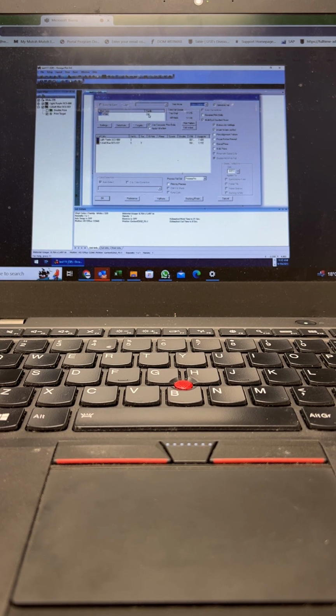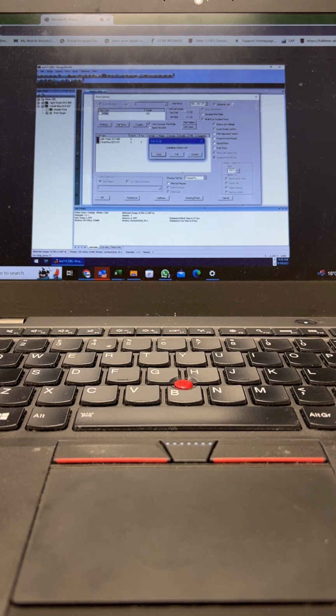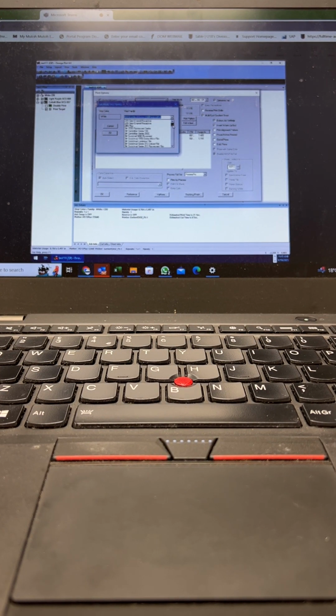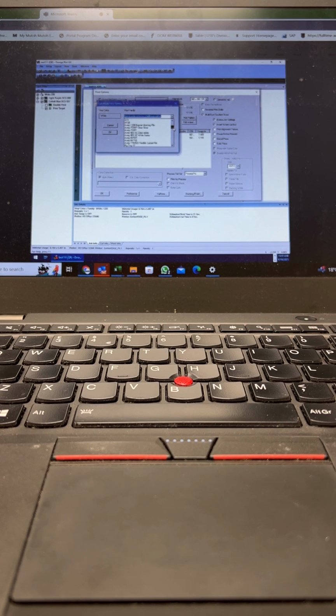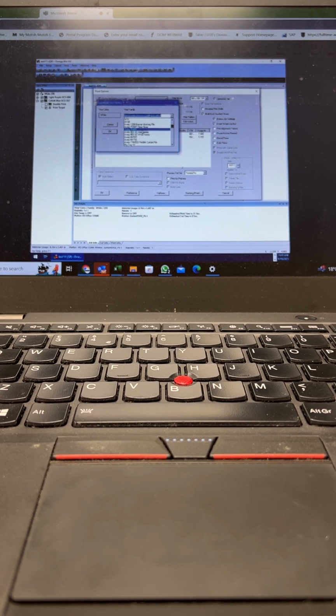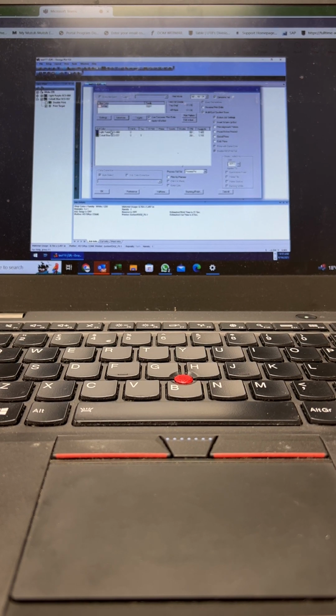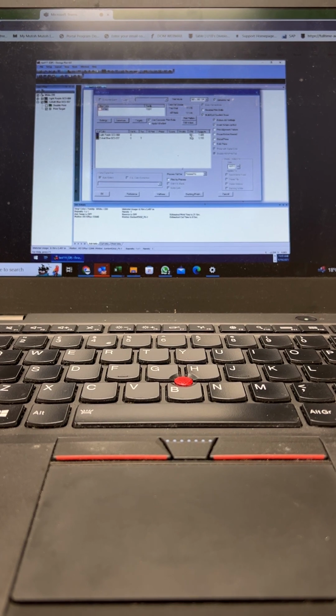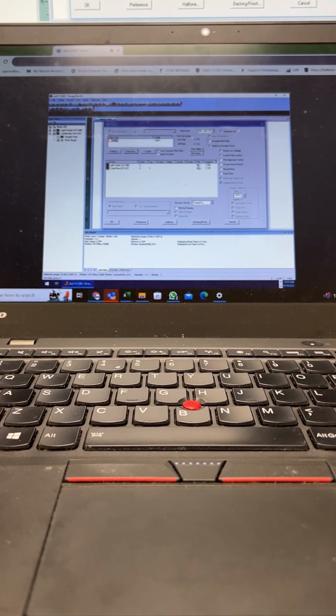If the customer is not printing on 220 vinyl, and instead they loaded Avery, for example, you can select that and go to Substitute and Vinyl, and then you'd want to select the material that they're actually loading into the machine. So if they're loading Avery 700, you would select that, and now it knows what settings to use for those foils and materials. So material selection is important with the Gerber software when outputting to get good results.